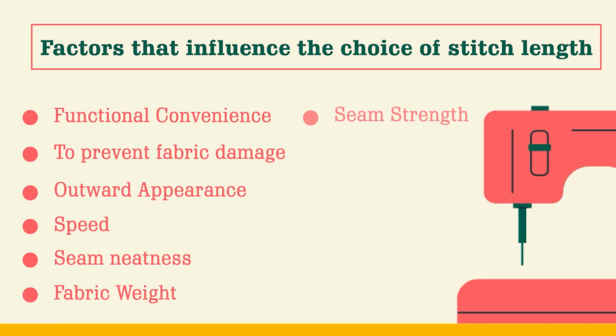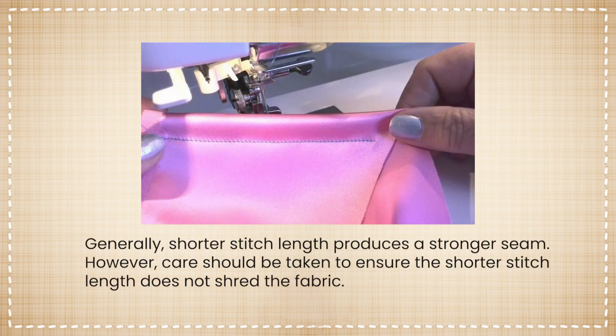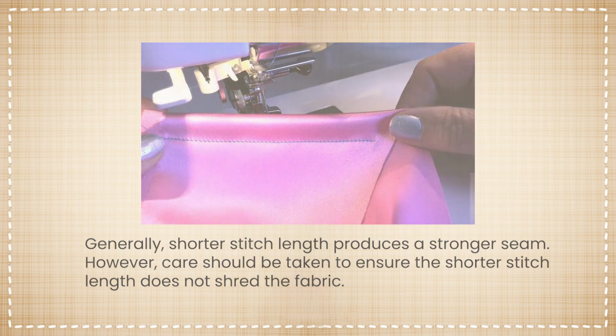Seam strength is also another important factor. So generally, shorter stitch length produces a stronger seam. However, care should be taken to ensure that shorter stitch length does not shred the fabric.